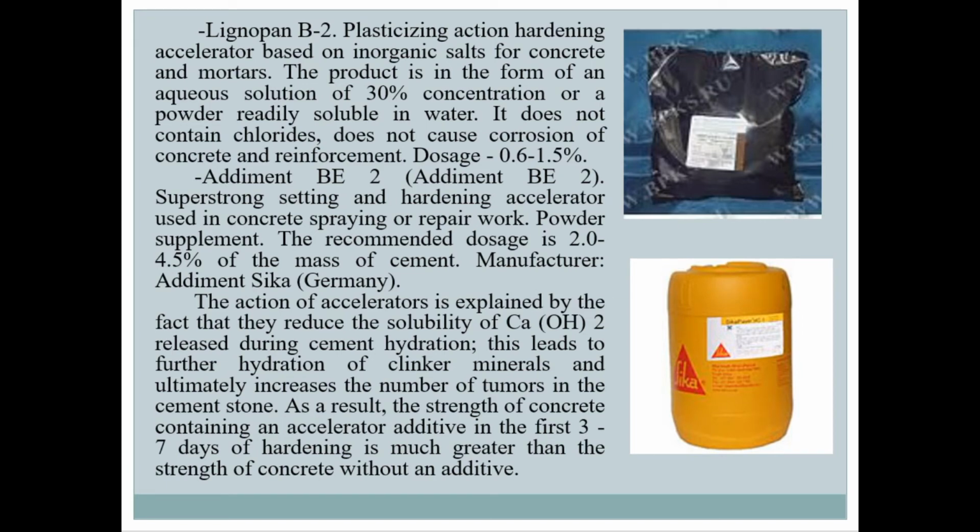Lignopen B2, plasticizing action hardening accelerator based on inorganic salt for concrete and mortars. The product is in the form of an aqueous solution of 30% concentration or a powder readily soluble in water. It does not contain chlorides, does not cause coloration of concrete, and reinforcement dosage 0.6 to 1.5%.